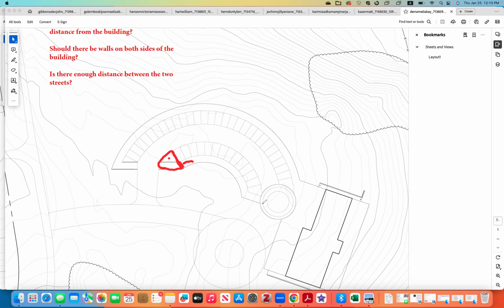Right. So this double line, that's the curb, right? The curb might stop right there. And then this is your vegetation as well. And then your sidewalk actually needs to continue. Does that make sense? It continues, and then you get to the plaza, and you would want your plaza edge to form a 90-degree angle with your curb over here.